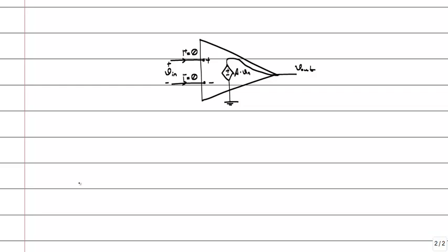That large voltage comes from the sources, V plus and V minus. So actually there are two more connections to the operational amplifier. There is a positive DC voltage source and a negative DC voltage source. Okay, the necessary voltage comes from those cables. You apply a small voltage, at the output you will see a large, amplified voltage.